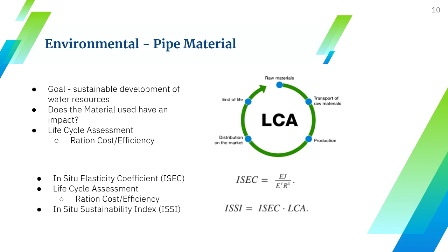So first, we look at the pipe's hydraulic behavior, which is the interaction between pipe and water in relation to the hydraulic operation of the network, and the static behavior of the pipes, which is the interaction between pipe and laying it in the soil in relation to the forces acting on the pipe-soil system. The pipe static behavior characteristics in relation to the soil are defined depending on its rigidity and its aptitude not to deform due to load.